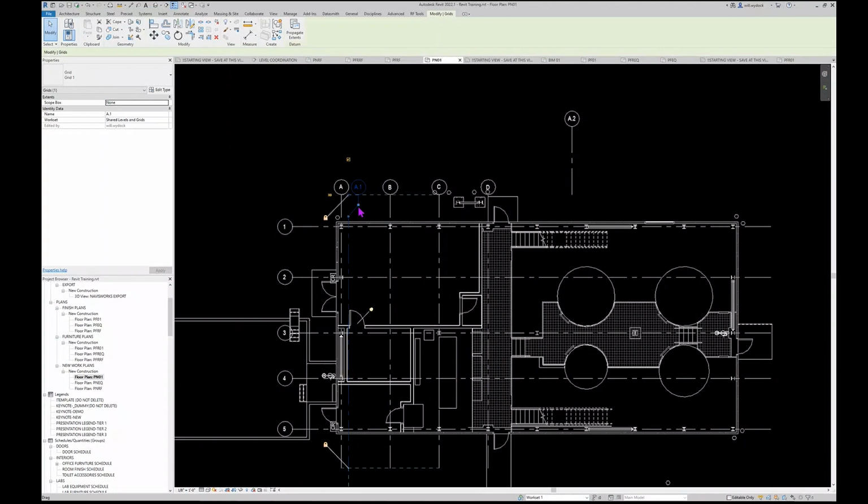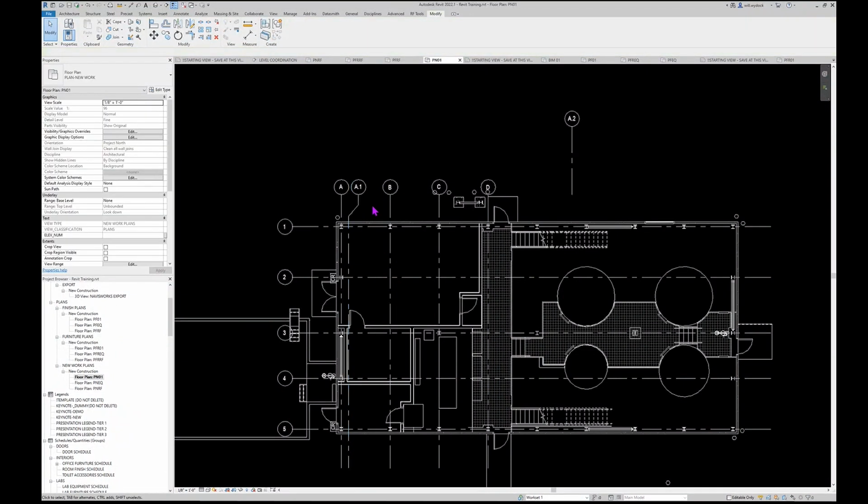I didn't have to sit here and manually add this elbow each time. The bad thing about propagate extents is this only works when views are not cropped, either the source or the destination. Once these are cropped, that feature doesn't work. So if you introduce a grid line after you've already cropped your views, because we know it happens, and you don't fix these type of features before you start cropping your view, there is no easy button, and it becomes manual for every view. So this is another thing to think about with your graphics.